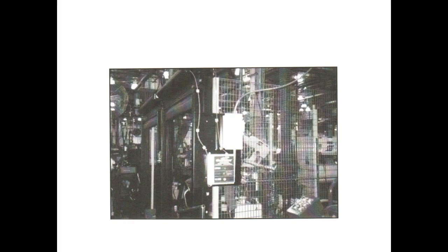But if you're in automatic mode, it's set up right. As soon as you open up a door to go inside, or as soon as you go through a light curtain, or as soon as you step on a pressure mat, then what should happen? The robot should stop. Now the robot stops, and you have to reinitiate the program, right? You don't have to start it over. You just have to tell it to start from where it's at.